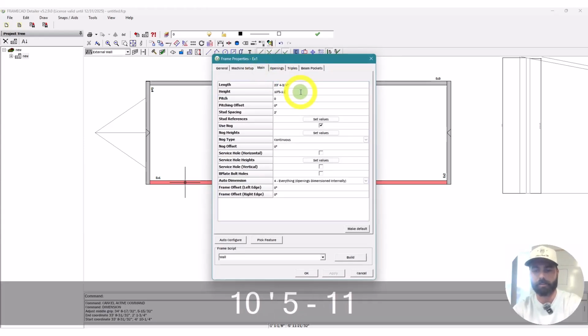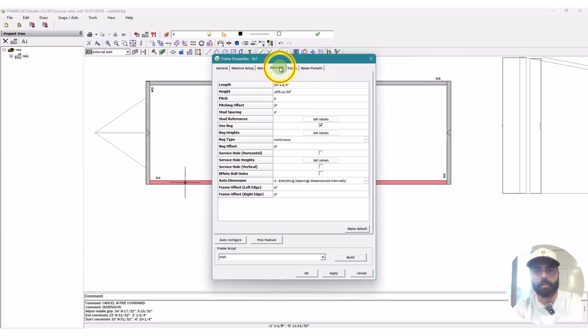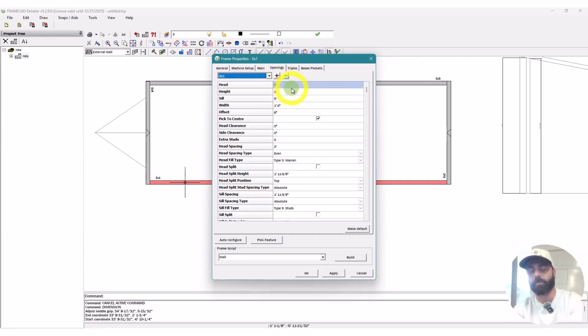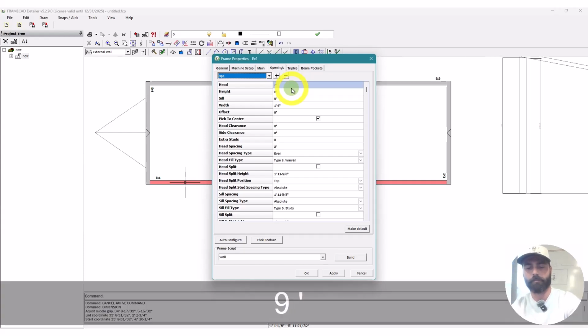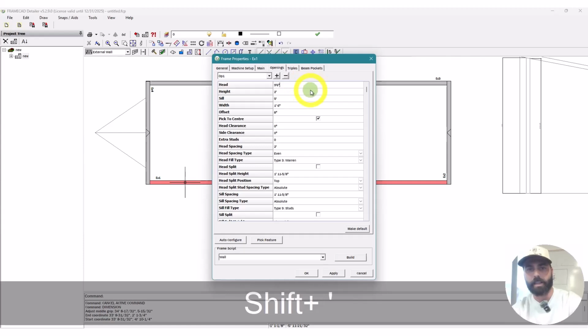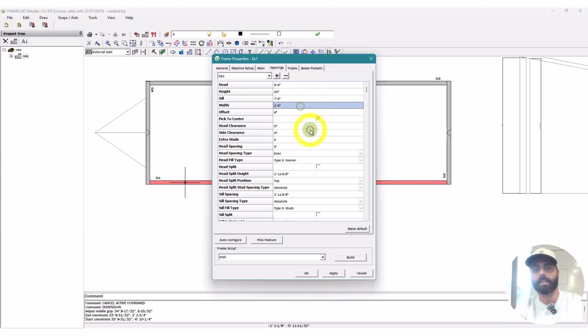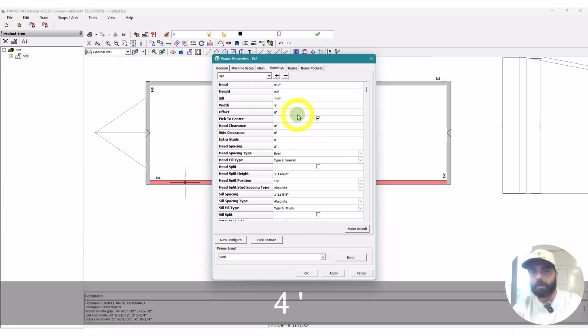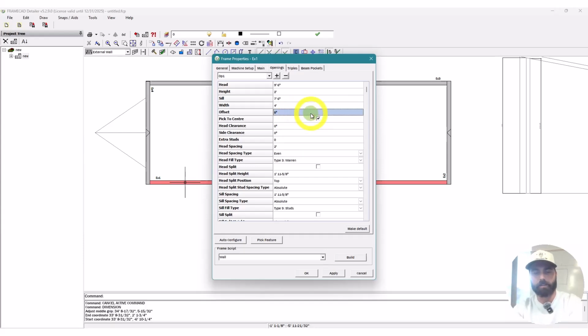And then we'll add some openings. You're pretty commonly going to have some clerestory windows in tiny houses. So we'll put these at 9.6. We'll say that they're 24 inches. That's putting you at a 7.6 sill height. 48 inches is pretty common, 4 to 5 feet. We'll offset this a foot off of the end. Now, if you wanted a foot off the end, the one thing that we need to account for is how we lapped that panel. So you could either offset this in the script and move it manually. That would be 9 3/8.